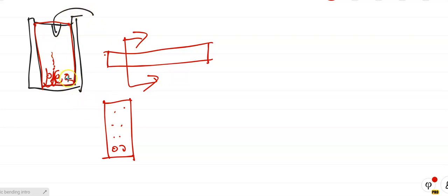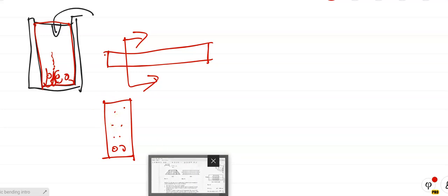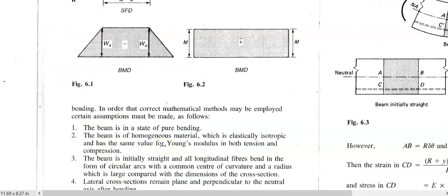The stone is blasted out of a quarry, and it's placed, it is vibrated, it is poked with the machine, and at the end of it all, the beam stands. So if we did an analysis on it, the material isn't exactly homogeneous, but if it's correctly placed and vibrated, as it's supposed to be, then we can safely assume that the material is homogeneous. That means if it's stressed, it will behave the same way throughout elastically. If we squeeze it or stretch it slightly, and we don't over-squeeze or overstretch it, when we release the forces on it, it will come back to its original shape. That means it will behave elastically.